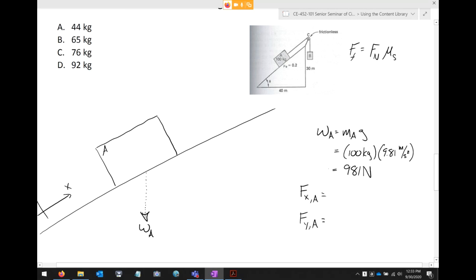All right, so we're going to take the weight multiplied by something. Okay, now this slope ratio, this is 30/40. So this is again another 3/4 slope ratio, which by the way, is pretty common on this section of the exam because it's a 3, 4, 5. 5, 12, and 13, that's another common one. I think it's 7, 24, and 25, 8, 15, 17. Those are all pretty common instances of slope ratios you see on the exam. And then there's also some simple ones like 1-to-1 and what have you.